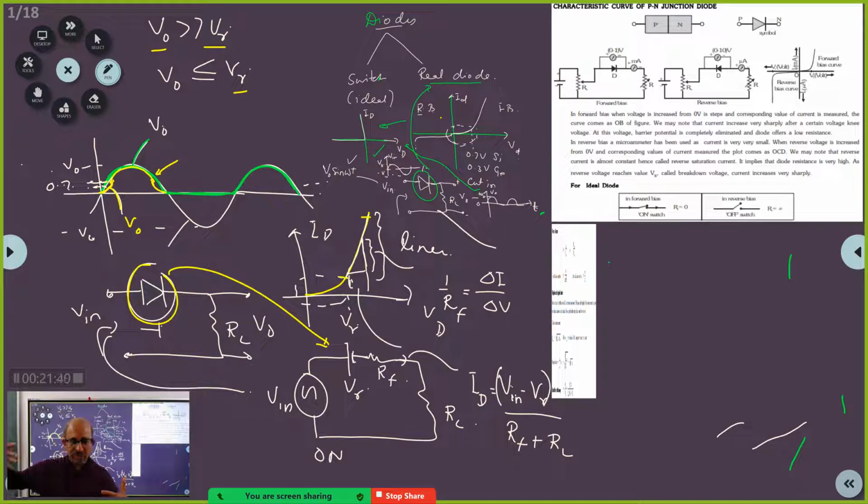The diffusion current is moving like this. But at the same time, the depletion layer is trying to form. It is not that once the diffusion current starts flowing, the depletion layer will not form. No, it is doing its best to form. That resistance is there. That is why we are using the concept of potential energy barrier.